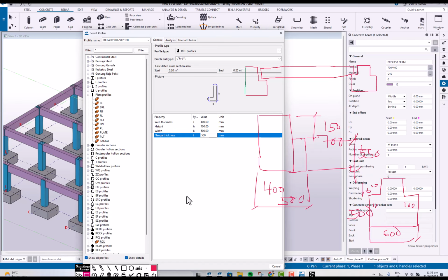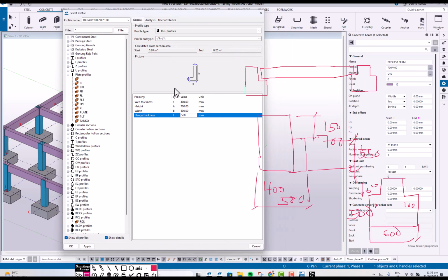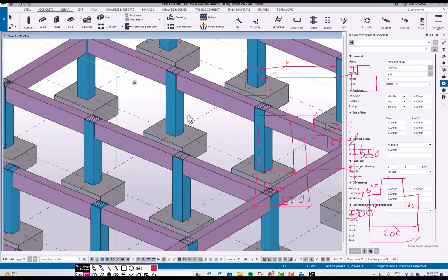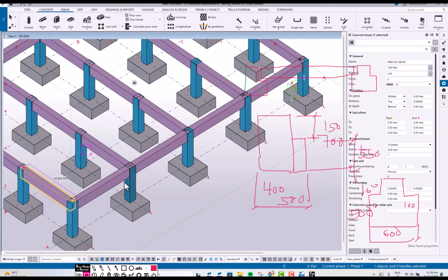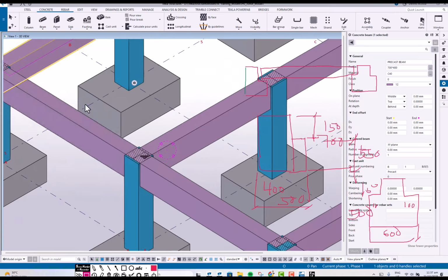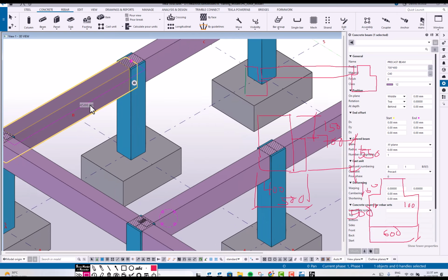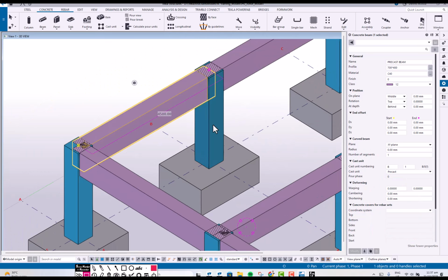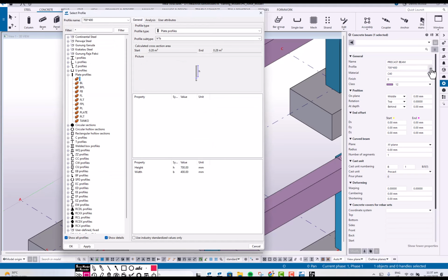Okay, again, can you look onto that one? Can you follow that? You know where to go? Here, again, from select one beam, okay? Just select one beam. Oh, I'll delete this one, huh? Anyway, we know already the value. So select this beam, and then from the profile, select the library, the database of the profile, and then look for the RCL. This one, RCL.